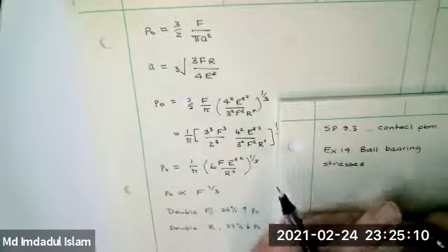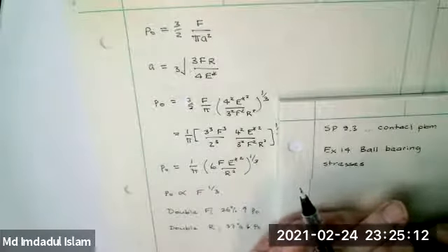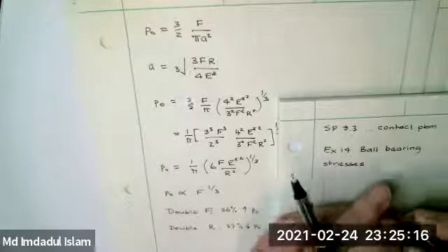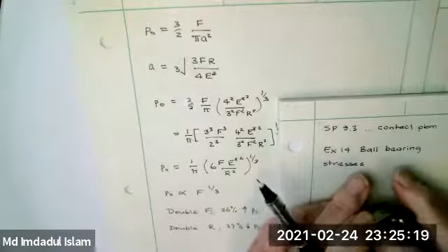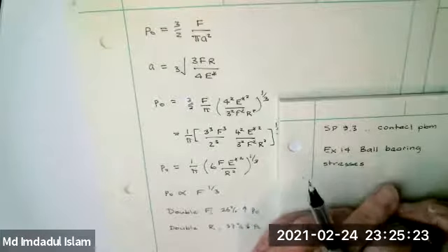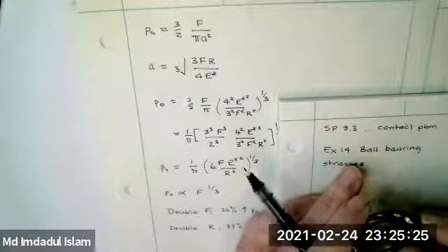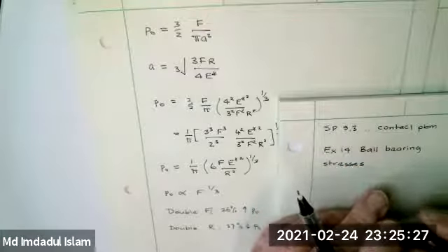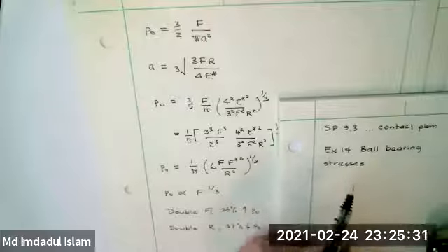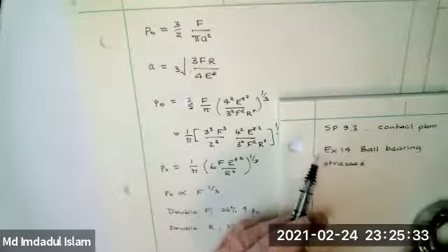But the stresses will be reasonably high under moderate loads. Why is that? It's because the contact areas are small. On the other hand, what's forgiving is the shear stresses are not that high. And so as a result, you can live with it without fatigue. So we'll do an example like this. But are there any questions now?